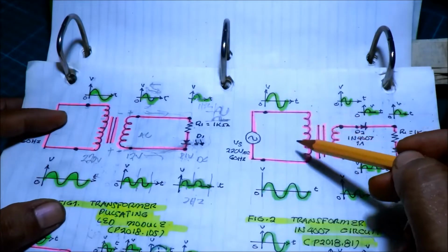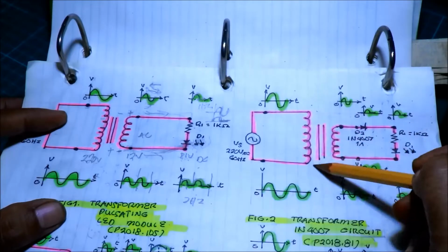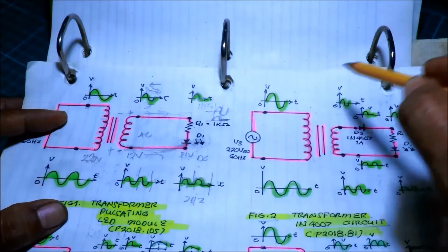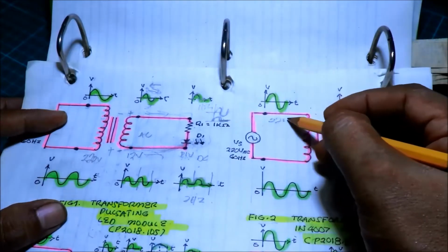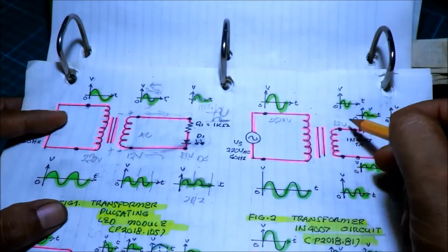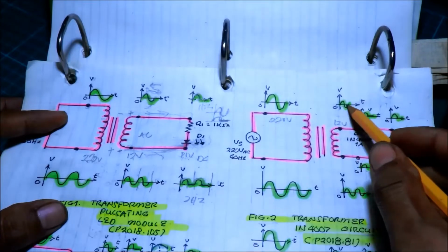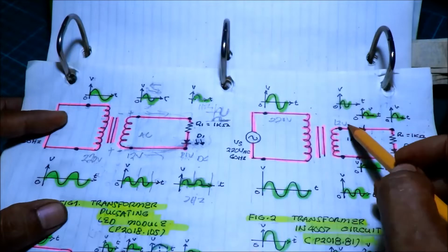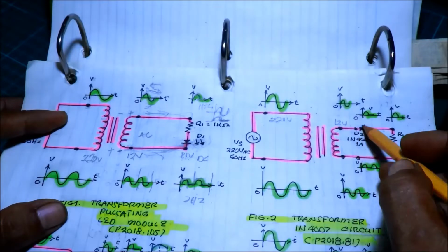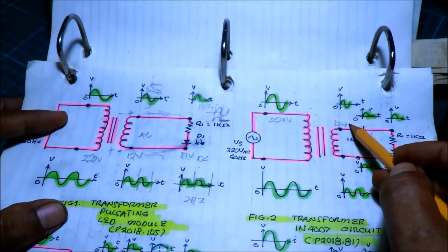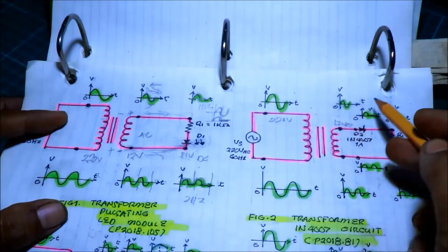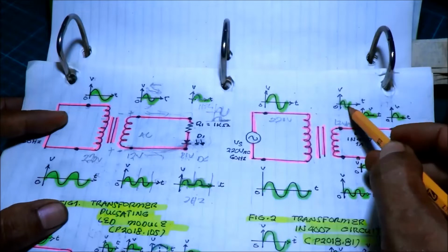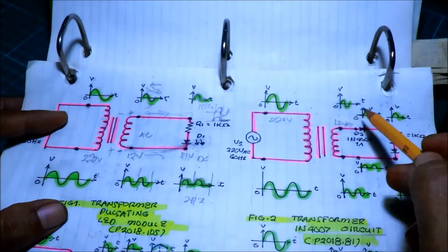So in this circuit, we have also the transformer, the secondary, primary, a big sine wave, 220 volts becomes 12 volts again. The big sine wave becomes the small sine wave here. Still in the secondary, it is 12 volts AC. This one. So again, during the positive half cycle, as I've said,